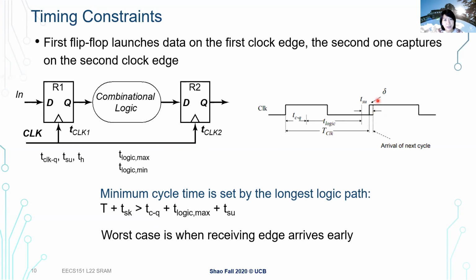So how would that change the delay analysis that we discussed earlier? This time, we think about the overall latency here. We still have our clock to Q delay. We still have our combinational delay. We talk about our setup time. The setup time is between this input and the clock of the second flip-flop, in this case clock 2 here, right? So the setup time is between this dashed line and this dashed clock, because this is the clock that we really need to monitor for the second flip-flop here. So with that, we have a longer setup time.